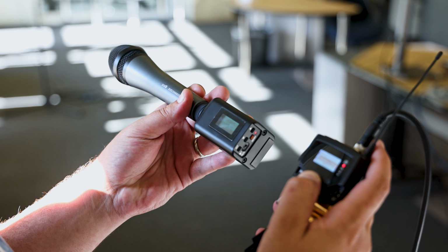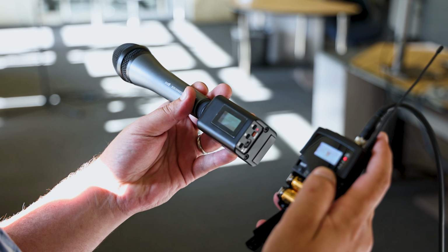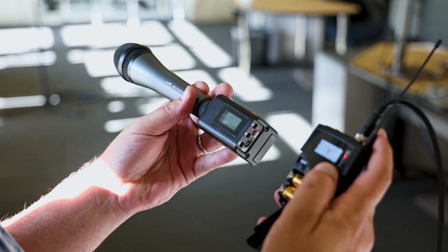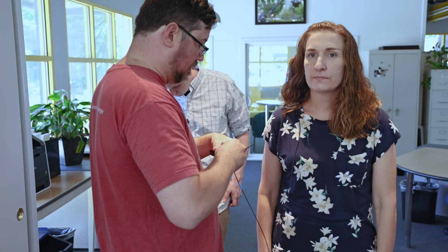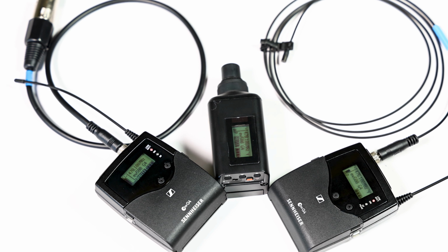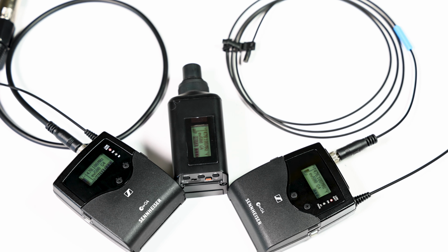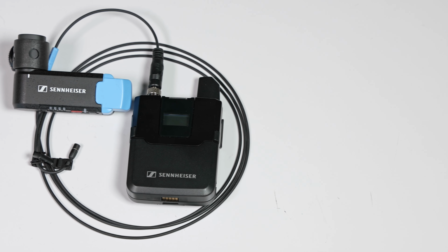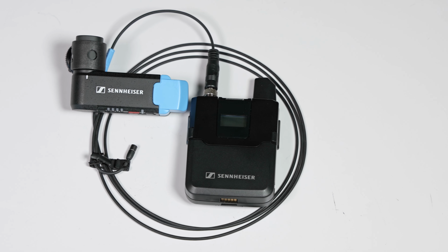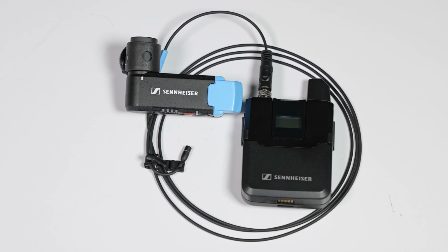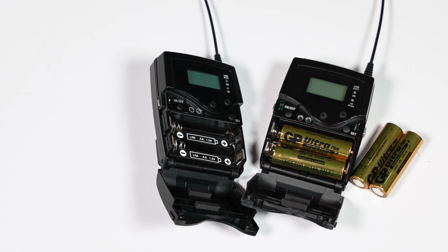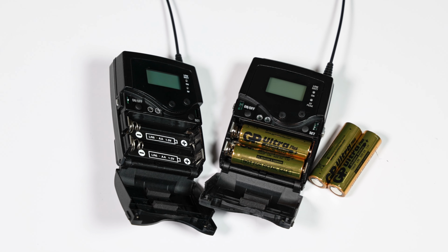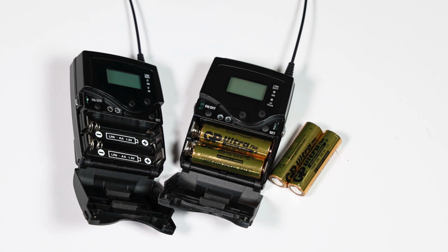Before using a wireless microphone, make sure to do a channel scan to ensure it doesn't have any interference. Make sure you understand how to do this with every wireless mic you use. It'll allow you to find a wireless channel that will allow you to get a clean capture. Make sure both your transmitter and receiver are on the same channel. Digital wireless systems like the Sennheiser AVX find the cleanest frequency in the 1.9 GHz band as soon as you power up the receiver. Be mindful of the batteries on both the transmitter and receiver of your wireless system, as they are a typical culprit of improper function.